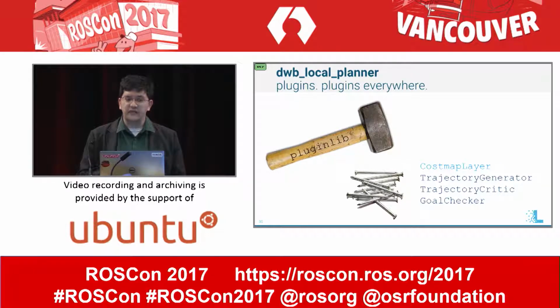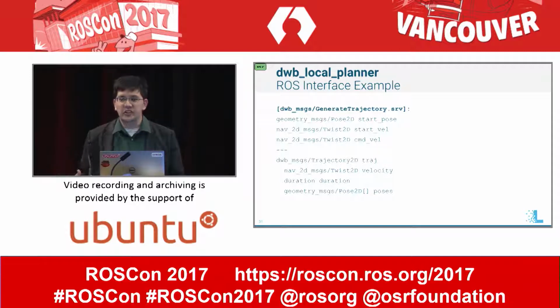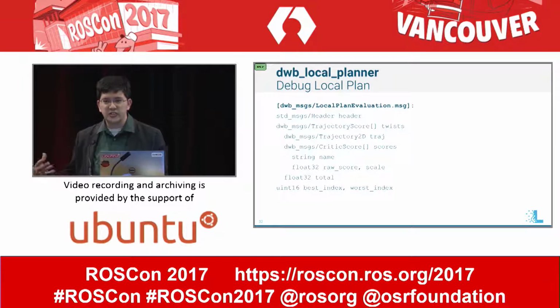But in addition to the plugin interfaces, we also have ROS interfaces for each of these. So the generate trajectory also exists as a service that you can call, where you give it a start pose, start velocity, and command velocity, and the result is a trajectory, a series of poses. Similarly, while you're planning, you can also generate this local plan evaluation message. And that has all of the trajectories that were generated, the poses that they go through, and the scores from each of the critics for each of the trajectories. And that way, when you're sitting there afterwards and it's like, why did my robot do this? You can actually go back, check the logs, and see.